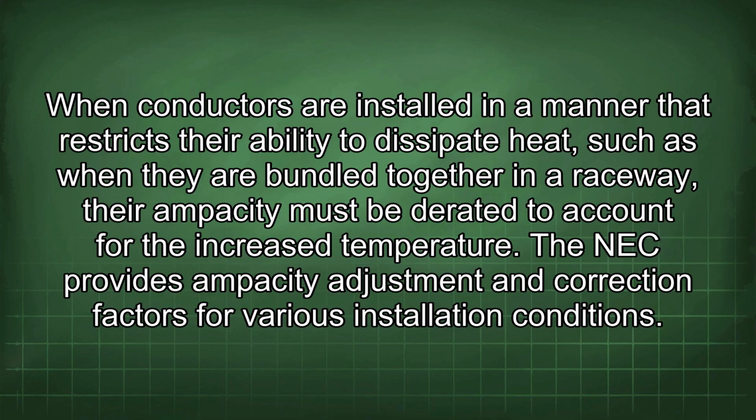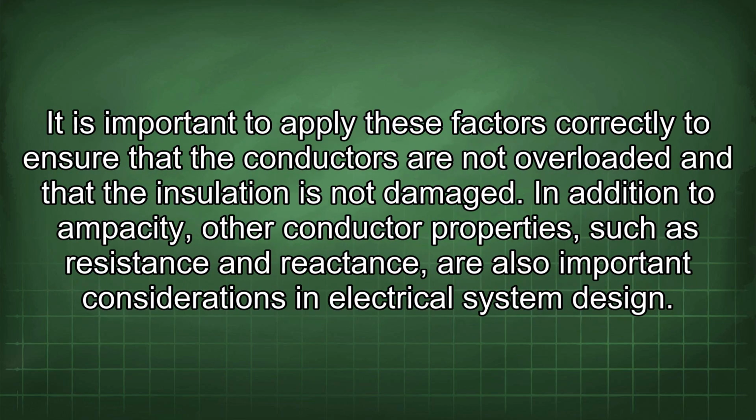When conductors are installed in a manner that restricts their ability to dissipate heat, such as when they are bundled together in a raceway, their ampacity must be derated to account for the increased temperature. The NEC provides ampacity adjustment and correction factors for various installation conditions. It is important to apply these factors correctly to ensure that the conductors are not overloaded and that the insulation is not damaged. In addition to ampacity, other conductor properties such as resistance and reactance are also important considerations in